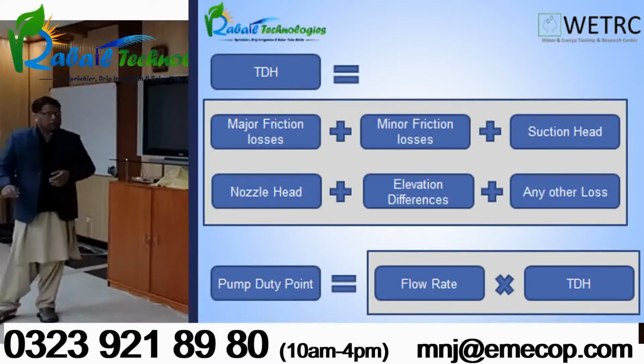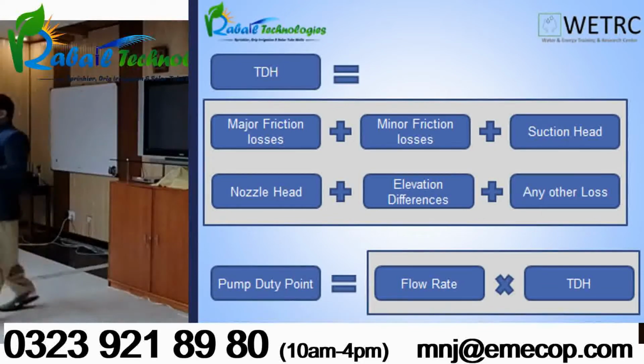What are minor losses? We have calculated friction losses in the piping network, but in a piping network, you must know there are elbows, there are T's, there are reducing bushes, sudden contraction, sudden enlargement, there are valves, a barb connection of the dripper or the thread connection of the sprinklers. All these we call minor friction losses.